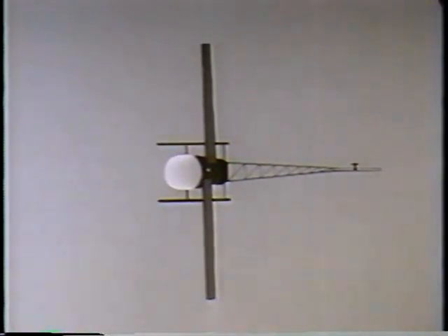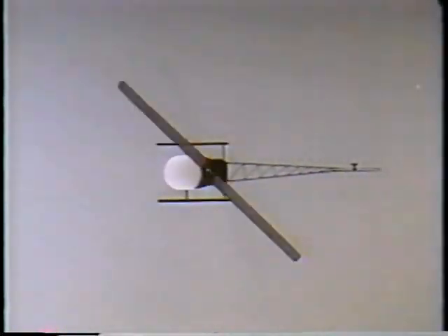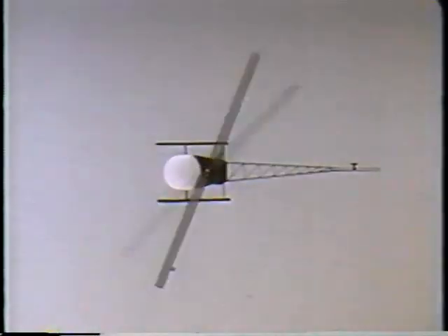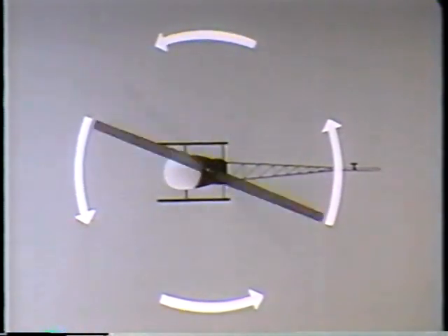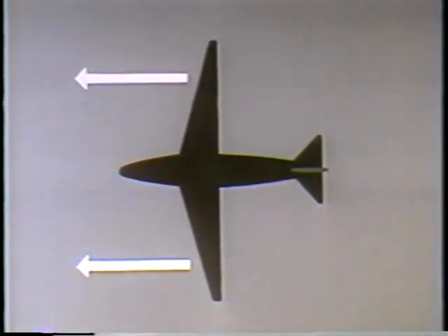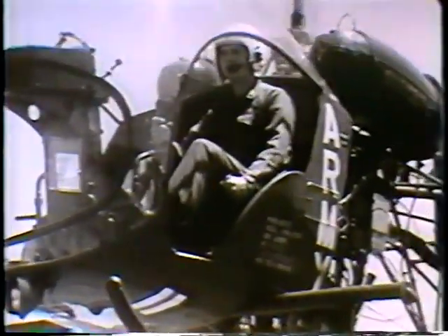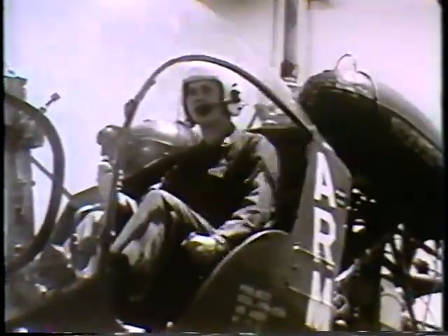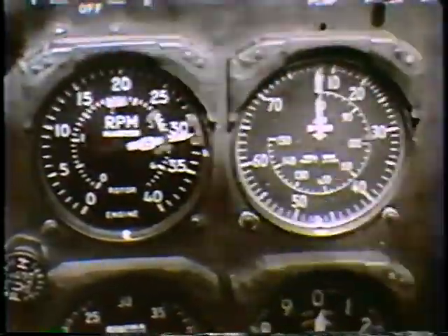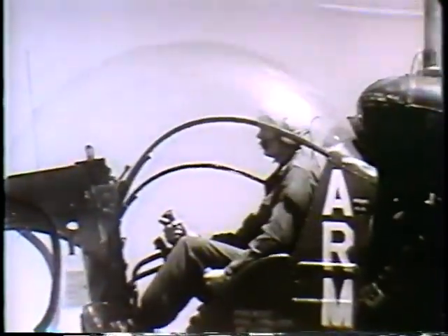In other words, the rotary wing performs the same function for a helicopter as a fixed wing for an airplane. The only difference is that in order to produce lift, a rotary wing flies in a circle, whereas a fixed wing moves forward through the air. Whether a helicopter is in flight or at a hover, the pilot maintains a constant rotor RPM. Therefore, the way he varies lift is to vary angle of attack.